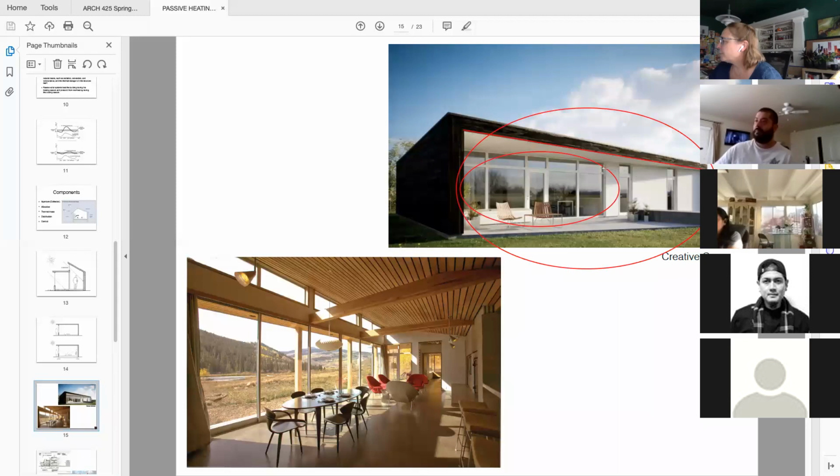And notice here where that roof is angled back, the solar glazing is a lot less in aperture size, so that in the summer there will be some direct gain coming through these openings because the overhang is not as deep, but the openings are a lot smaller. And then here, where you have the big, large openings, the overhang is a lot deeper.